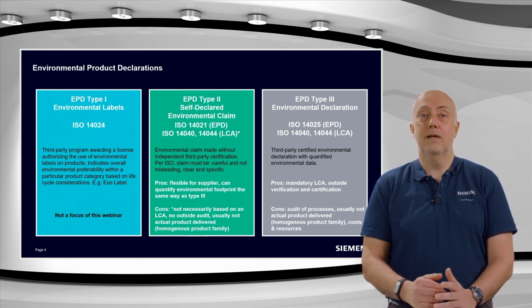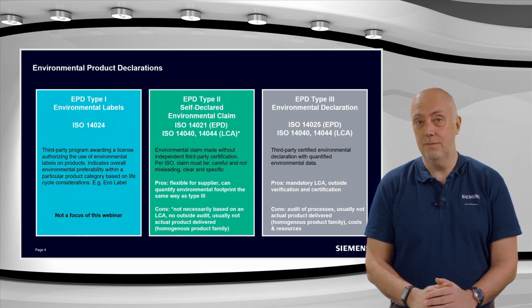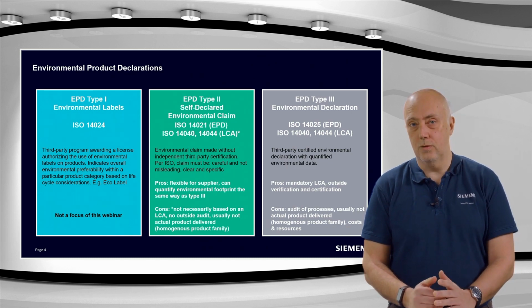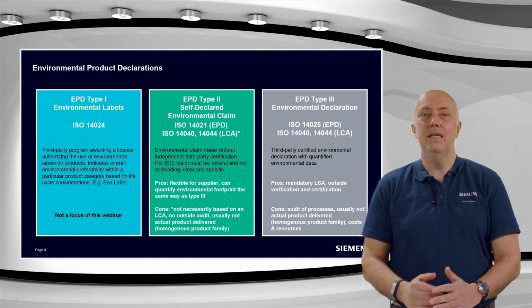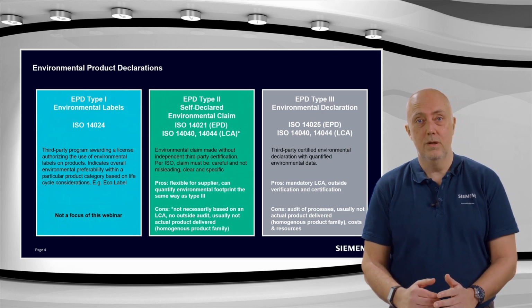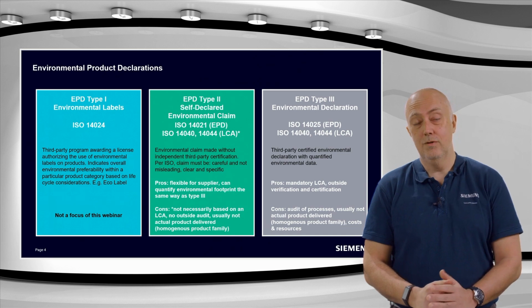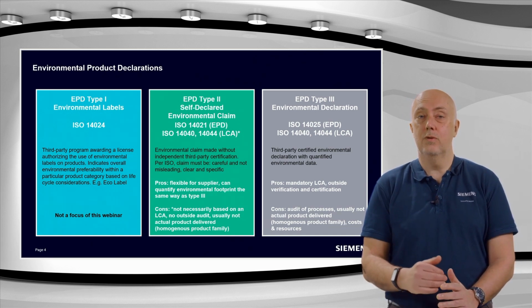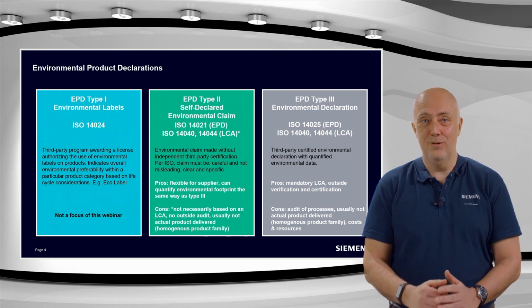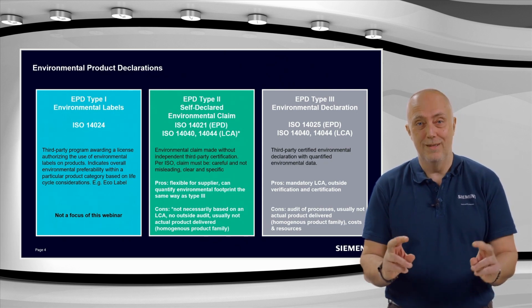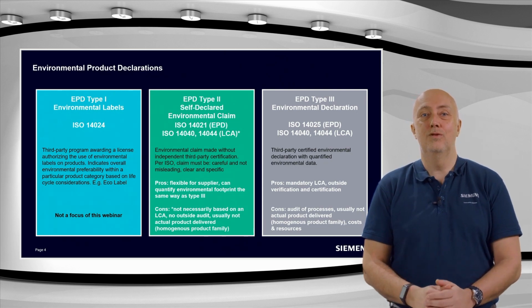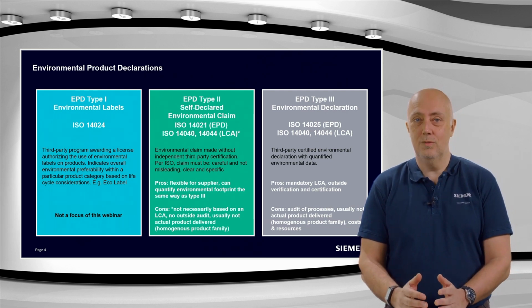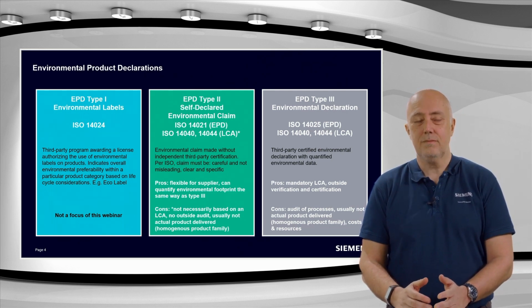The second topic I'd like to highlight is that EPD systems may use different sets of rules for conducting an LCA, meaning that the EPD results of the same product may differ from one system to another, which obviously is not ideal. And finally, the verification of your LCA doesn't mean that your final emissions figure is correct. It just means that you have followed the proper process and have documented your input and calculation.